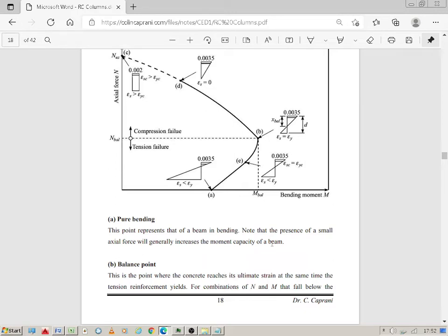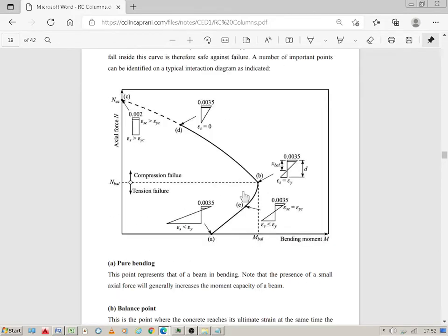Basically, it will move the neutral axis a little bit, and the concrete can take a bit more compression, because in a concrete section you've got a big amount of concrete, with only bars usually on the bottom in tension. So point B, which is here, I'm going to go back over this again, and I'll explain the diagrams. I'm going to do them bigger.